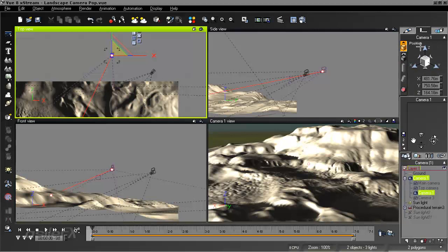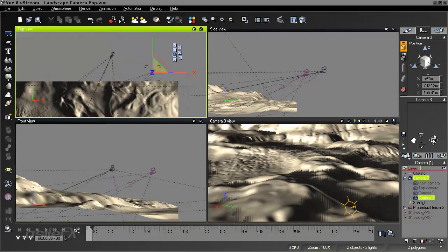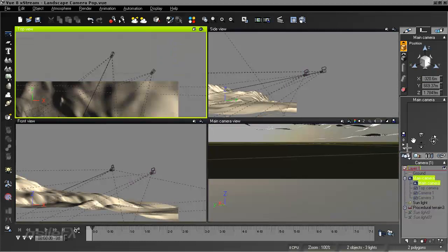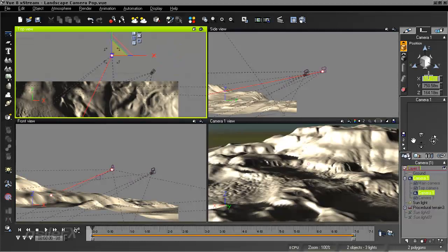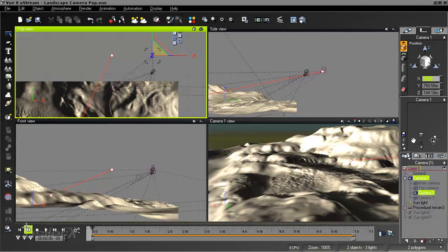And now we're going to move over to the numerics tab for camera 1, then switching over to camera 3 so we can copy over the information from camera 3, our original stored camera, for the first keyframe. So we can just select the numbers in there, Control-C to copy, switch the camera, and then we're going to need to add the position keyframe. And we might have to do that throughout.